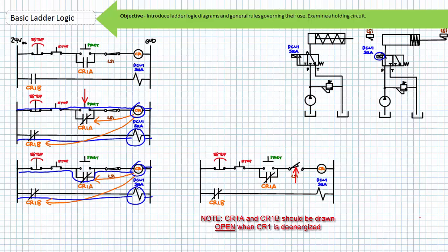Before we do so, let me remind you that hardwired, relay-based ladder logic is being replaced with programmed instruction sets written inside ruggedized computers called PLCs, or Programmable Logic Controllers. To change the functionality of an electrically controlled system employing traditional hardwire relay-based ladder logic, one must physically rewire the system. Our progressively more complex ladder logic examples illustrated this fact.